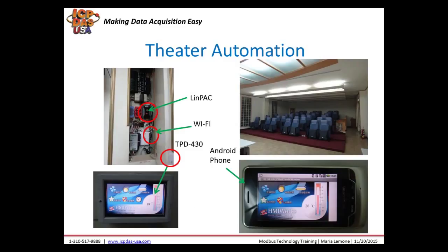So another scenario in this same type of application is you could also use a PC to run the web page, like InduSoft SCADA software could be connected to TPD430, the touchscreen PLC, and you could use that to host a web page too. It's an easier option to set up and you don't need to know a programming language.